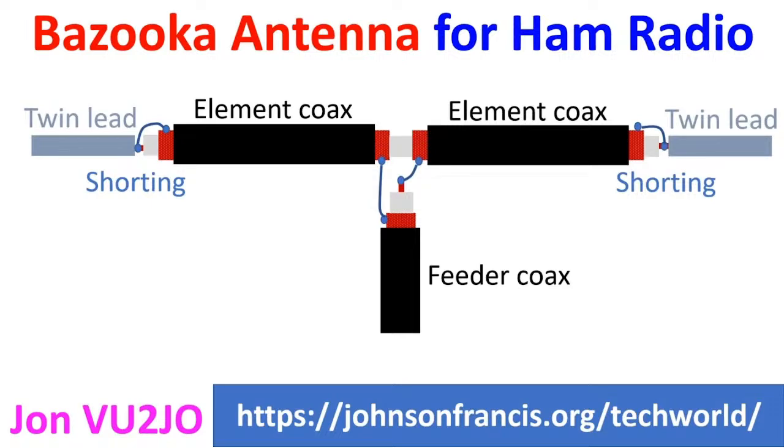Bazooka antenna is a single band antenna with a broad bandwidth within the band, unlike the dipole which has only a bandwidth up to 100 kHz. Moreover, Bazooka antenna does not radiate harmonics of the operating frequency and feed line radiation is very little. Bazooka antenna modified for ham radio uses does not need a matching balun and can be directly connected with 50 ohm coax. As the antenna has no exposed metal wire, static charges do not build up and reduces noise compared to exposed wire antennas.